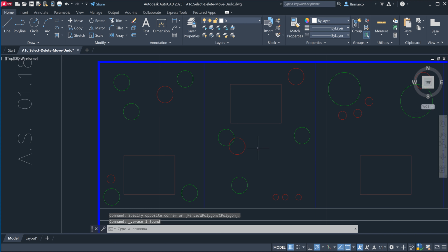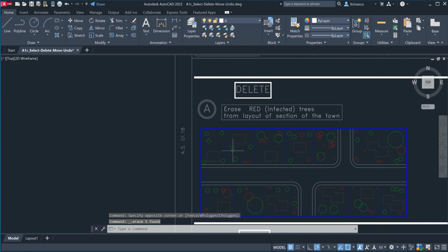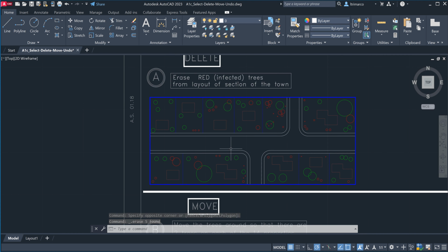You're going to get used to Control Z to undo. You're going to get used to selecting manually, one object by one object, or you're going to get used to selecting with little crossing windows. And I find I use the crossing windows more because I can select faster, and that's really the answer to that. So that's kind of typical A.